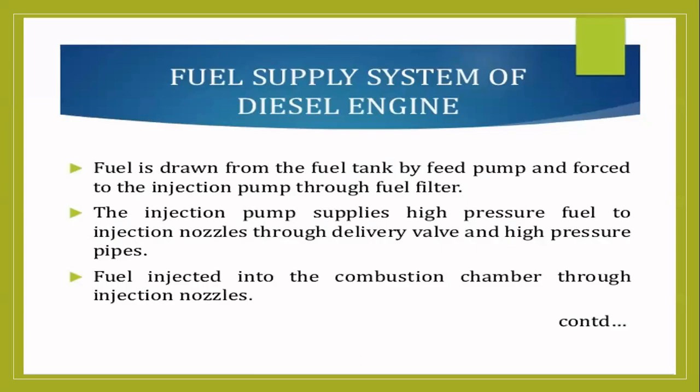Right? Fuel supply system for diesel engine. This is prepared for the final year. Some slides are not important, but they are also needed. You do not need to memorize. This is what is needed: fuel is drawn from the fuel tank by the feed pump. I already told you, fuel feed pump or fuel pump. Sometimes you want to write whether it is the petrol fuel pump or diesel fuel pump. Normally, if you write